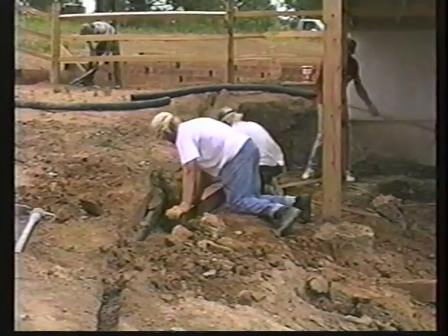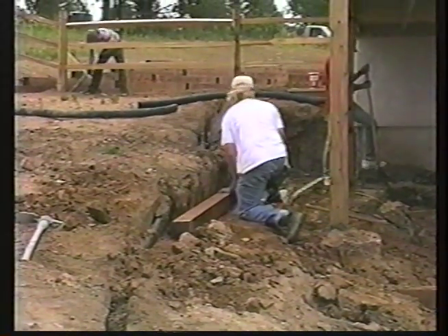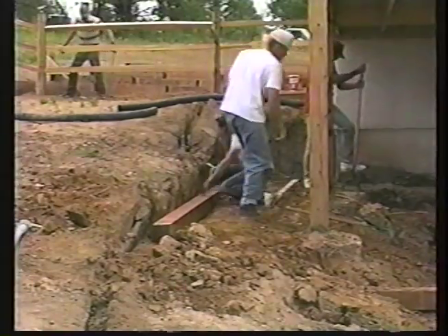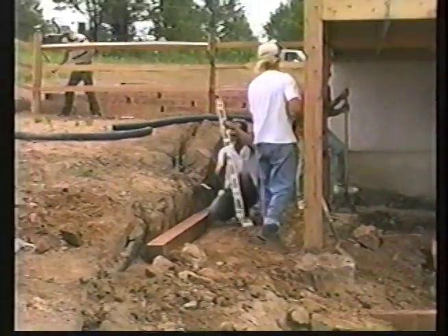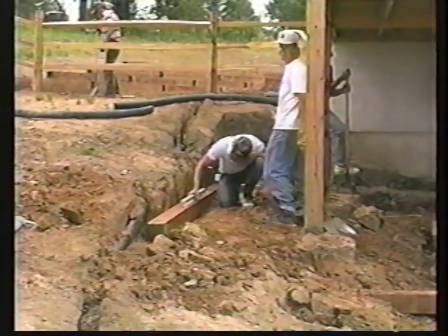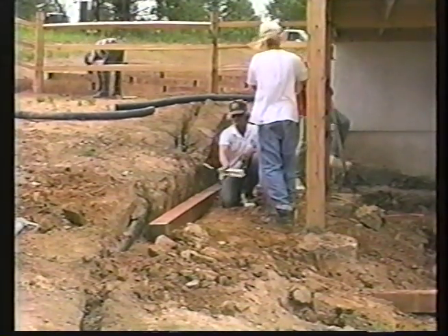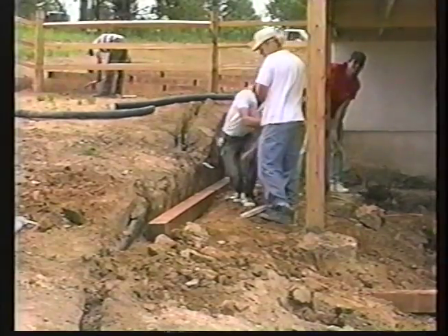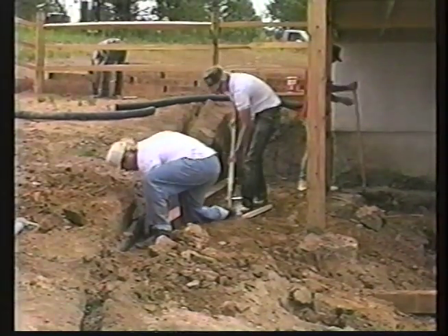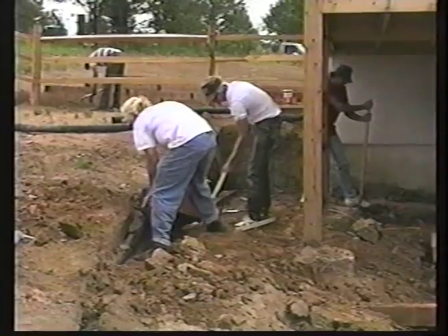Begin construction of your wall by running a string line along the length of the wall to keep the base course straight. It's important to choose uniform timbers. This will make all phases of your project easier. The proper installation of the base course is critical. It's essential that the first timber of the base course be installed at the wall's lowest point.